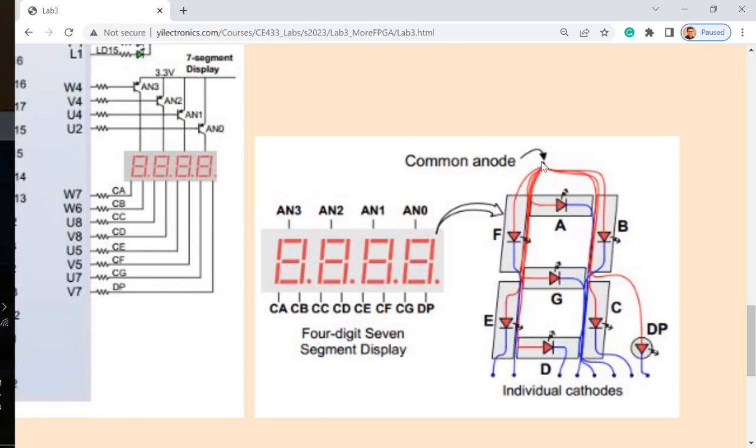I can show the circuit connection, since it's not really clear for you guys. Let me show you how to understand this point. So all the LEDs, see that? Represented by the red wires. These are the anodes of the LEDs, the plus terminal of the LED. They're being shorted to one node. The cathodes are left open. These are the cathodes of all the LEDs. You show different displays or turn on different LEDs by having this kind of circuit in the 7-segment display module.